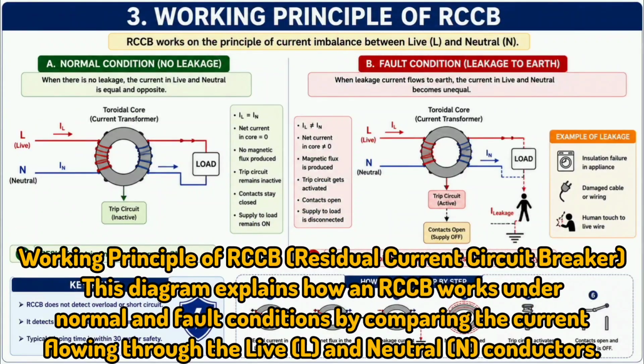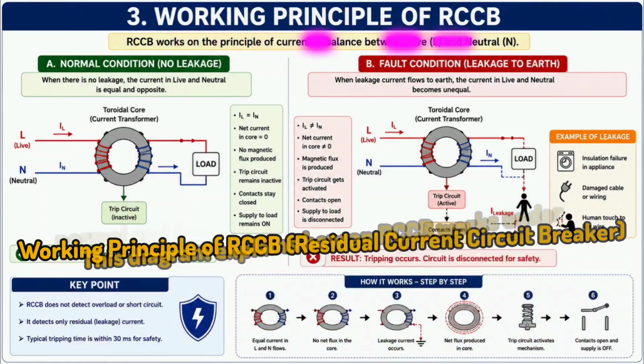Working principle of RCCB, Residual Current Circuit Breaker. This diagram explains how an RCCB works under normal and fault conditions by comparing the current flowing through the live, L, and neutral, N, conductors.